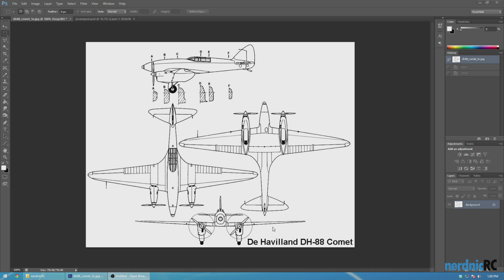I also need to see a front view, just so I can see dihedral or how stuff lines up. So by looking at this image, I know about how high off of the wing the horizontal sits, as well as how much dihedral in terms of degree. This will also tell me where my props are going to sit and everything. So this image is really important.